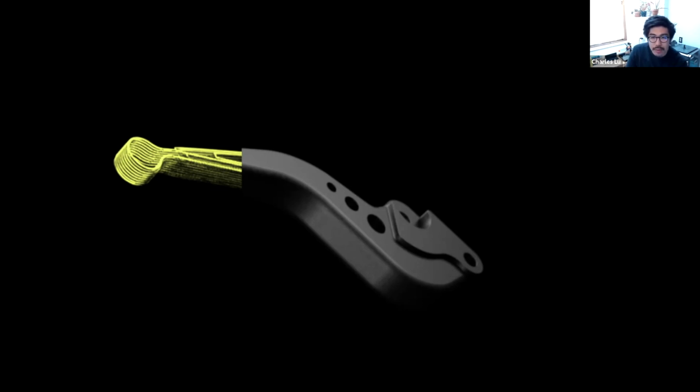Absolutely. So I would say that if you were to look at the material characteristics in the Z plane, you're going to see that behave just like the base plastic. I won't make any claims about that. We are 2.5 dimensionally strong. We're good in compression in Z. We're good in XY. But if you were to pull on a part, which you're printing layer by layer, it's like pulling a phone book apart, right? You're not going to see the strength there. It's going to behave like plastic in that sense, because the only strength that you're getting is the bonding between the layers.